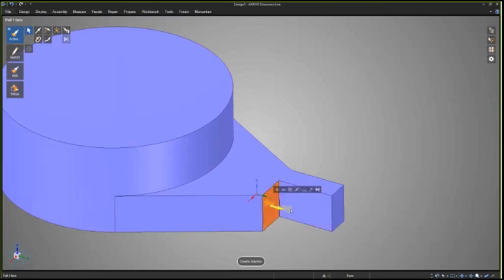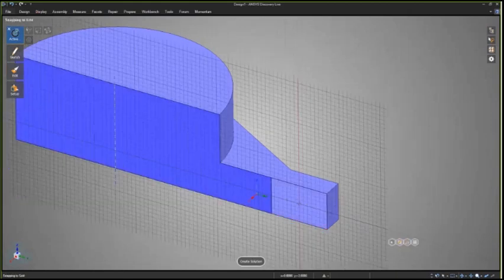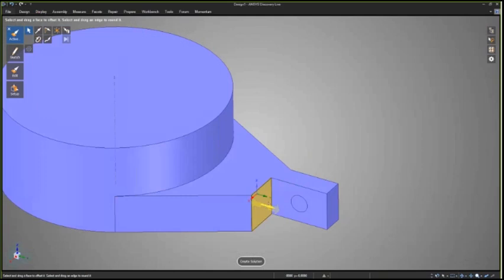And you'll notice there's a lot of things I can do directly to the geometry to make changes however I need to, but sometimes I may want to create something new. So I could always take another sketch tool and sketch directly on a face. Notice that I didn't set up any datums or anything like that, and I just hit P for pull, and I could immediately create a pin or a hole.